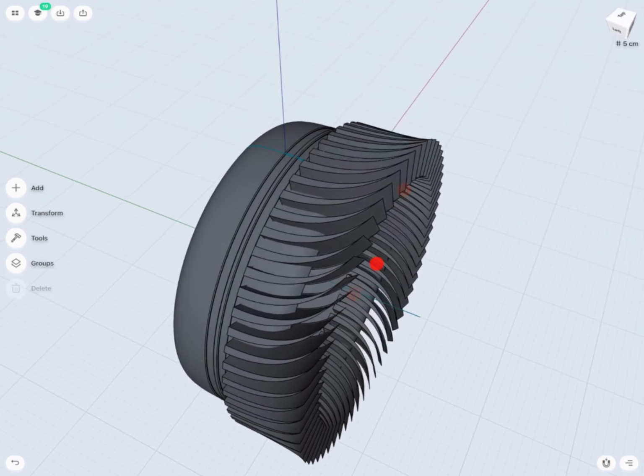I have to go to the top view, by just double tapping on a small box from the right top corner and then selecting the top view, and I'm going to create a line, and according to that line I'm going to mirror my cutting objects.